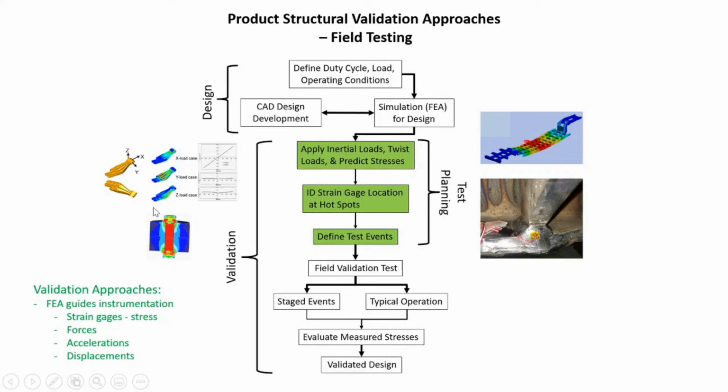And in addition to strain gauges, we may strain gauge bolts because all of the connections on the structure are very important. And sometimes we may want to put gauges on a bolt to measure its tension and bending loads as a part of an evaluation of that bolt-to-joint connection. And furthermore, the gauge locations often are going to be near welds. And so the welded joint areas are areas that we want to pay particular attention to in making sure that we have stresses in those ranges that are suitable based on welding standard curves and so forth.